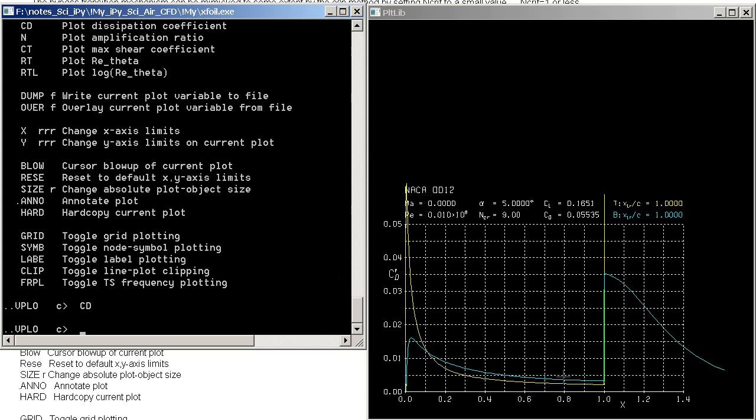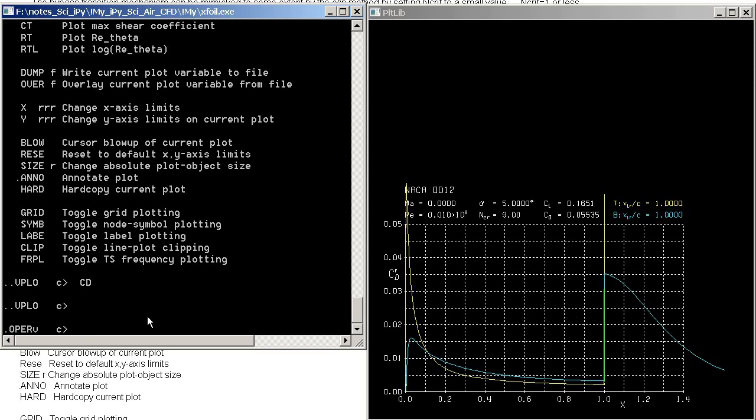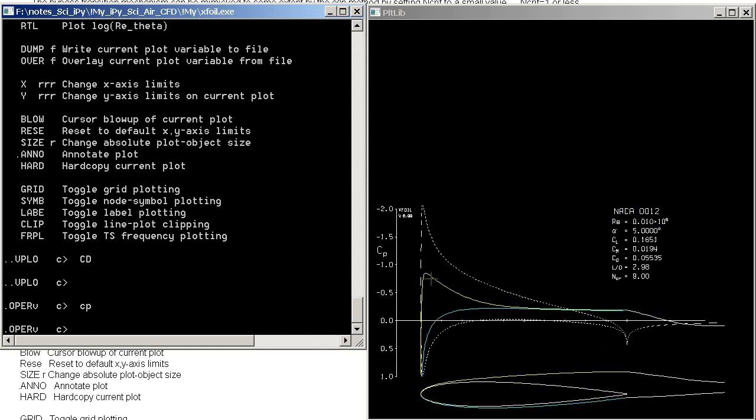And this graph is useful, and we know that, for instance, at the very tip of the airfoil, approximately 0.1, even less, we have a strong increase in the dissipation of energy. The same happens on the trailing edge. As previously, the yellow one is on the top surface and the blue line is on the bottom surface. Okay? So if you go back to our initial plot, the dissipation of energy happens here on the tip of the airfoil and on the tail.